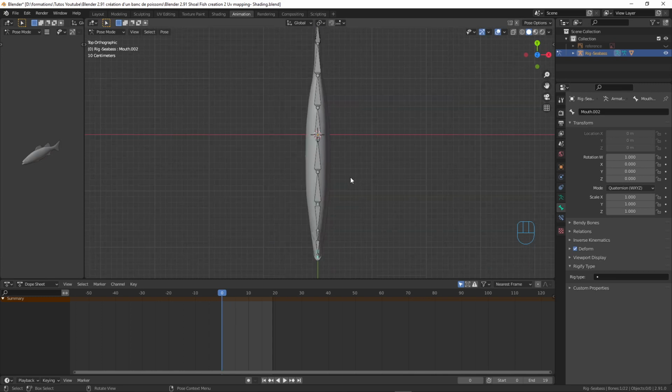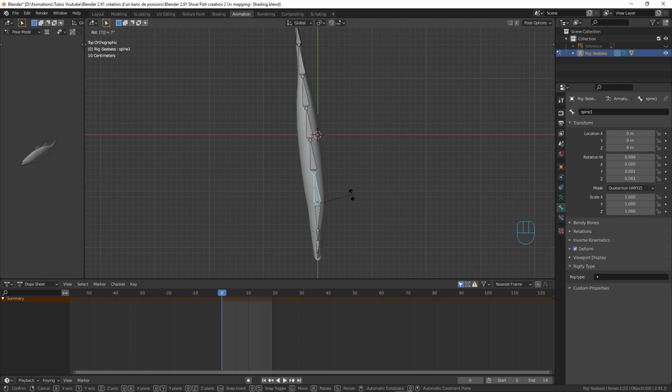It will be more understandable after, I think, when I do the job. It's difficult to explain. So let's go there, and I will take the first spine here, and I will make a rotation like that. I want to make a kind of shape like this, at first. So the first thing we'll do, we'll make a rotation, and we will select a value. I know that a value between 5 and 7 is good. So let's say I will make 7. Okay, so I just made R7.